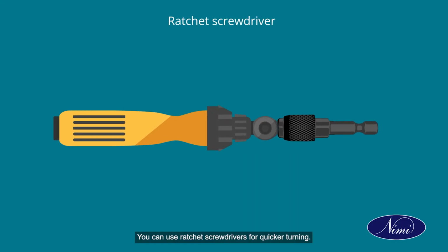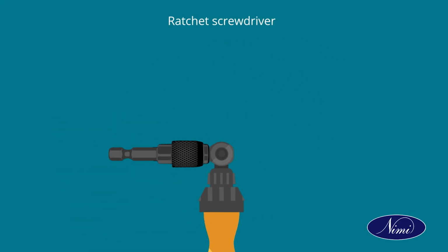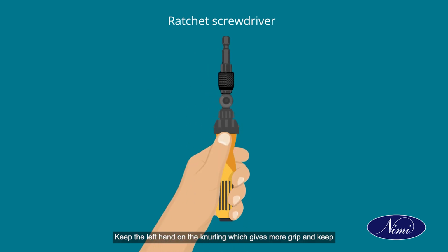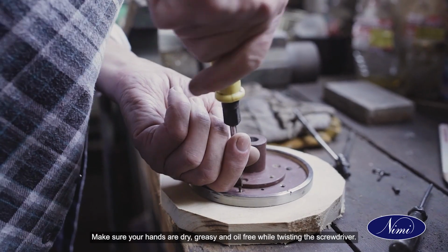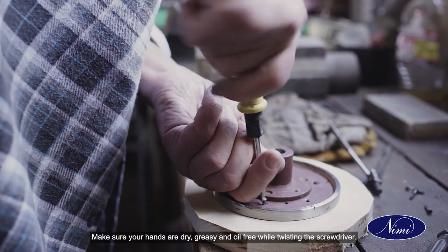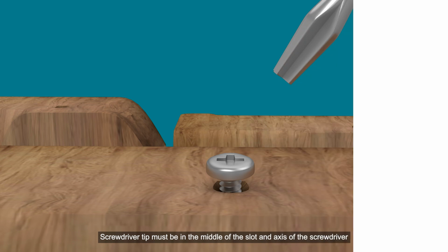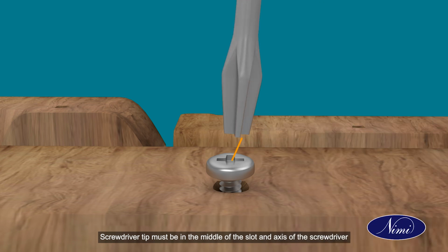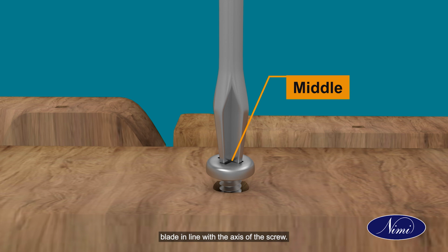You can use ratchet screwdrivers for quicker turning. Keep the left hand on the knurling, which gives more grip, and keep the right hand on the ratchet head. Make sure your hands are dry, grease and oil free while twisting the screwdriver. Screwdriver tip must be in the middle of the slot and the axis of the screwdriver blade in line with the axis of the screw.